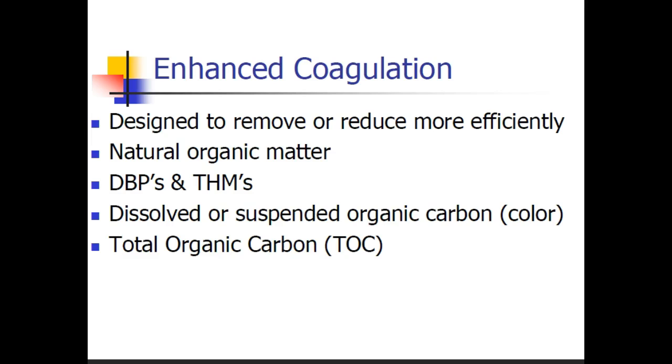Enhanced coagulation is designed to remove or reduce more efficiently natural organic matter, DBPs, disinfection byproducts, and THMs, trihalomethanes. Dissolved or suspended organic carbon, which is color, and total organic carbon, which is your TOCs.